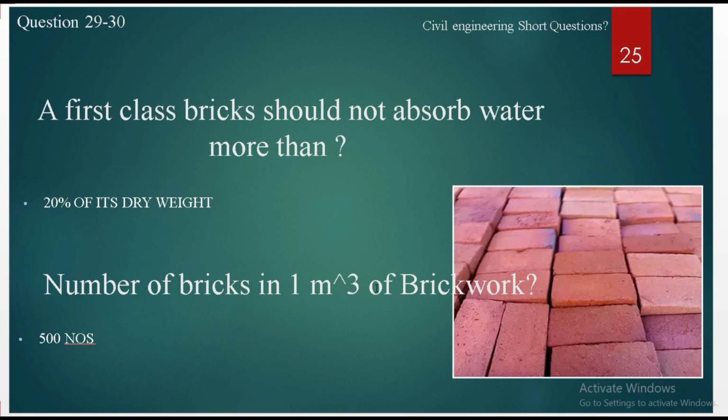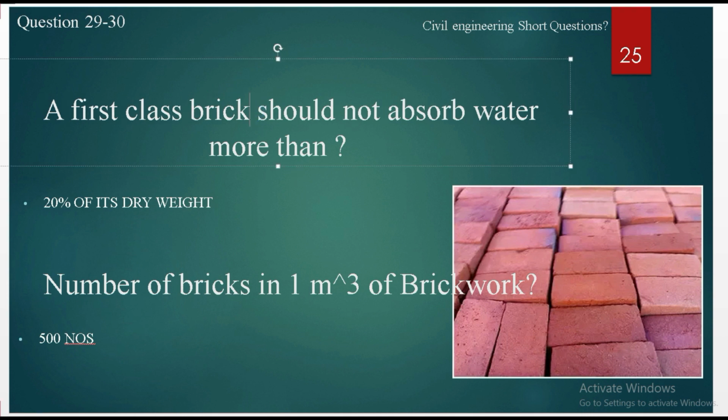Moving on. Question number 29 and 30. A first class brick should not absorb more than 20% water of its dry weight. So if you soak a brick for 24 hours inside water, its weight shouldn't increase by more than 20%, which means that if we have a 1 kg brick and soak it for 24 hours, the next day the weight shouldn't be more than 1.2 kgs. 200 grams is 20% of 1 kg.